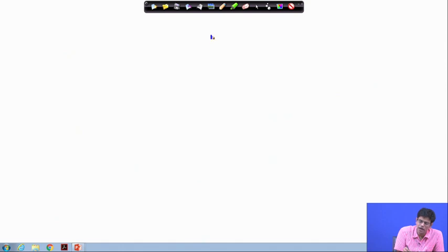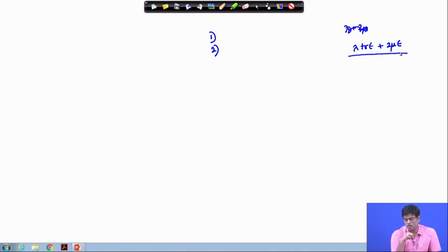So, in the first part we have derived Hooke's law, essentially for the isotropic material, for which our basic knowledge from strength of materials or solid mechanics applies. We have derived Hooke's law for an isotropic material, which, if you remember, is lambda plus 2 mu in this form, and if I write it in tensorial form, it is lambda trace of E plus 2 mu epsilon. So, this is the form.